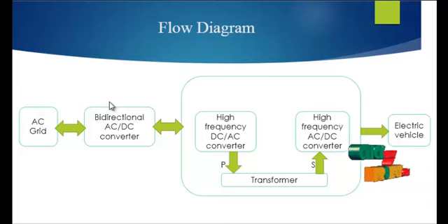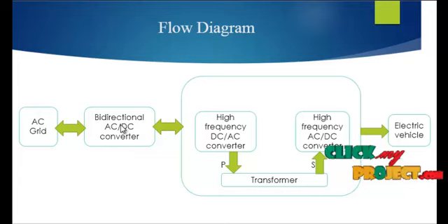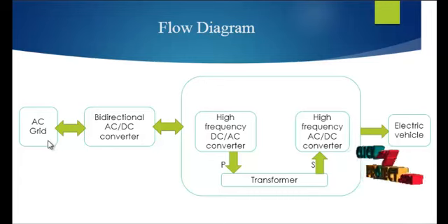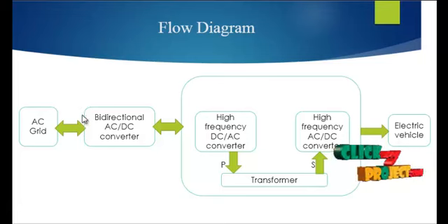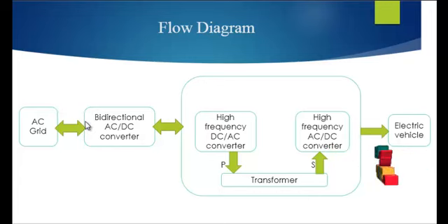A PWM strategy may be applied to accomplish voltage regulation of the DC side and current shaping of the AC side. Generally, BPWM and UPWM strategies are often utilized in single phase AC to DC converters. Here a simplified PWM strategy is proposed. The proposed simplified PWM only changes the switching status of the active switches.